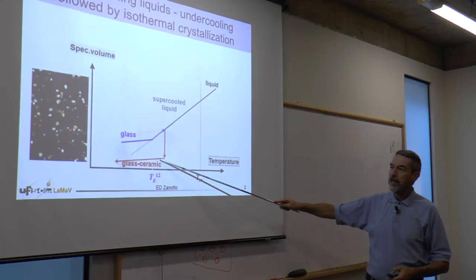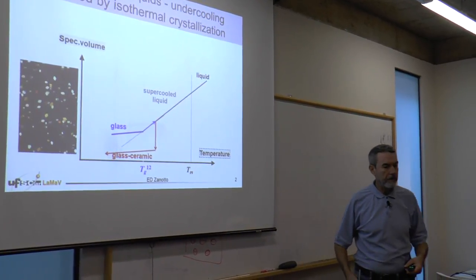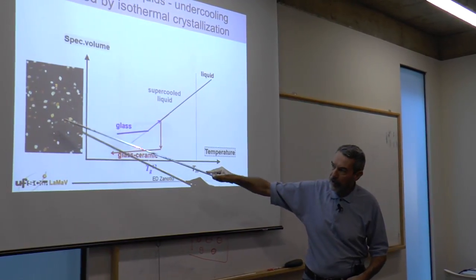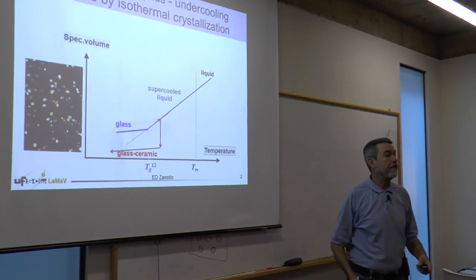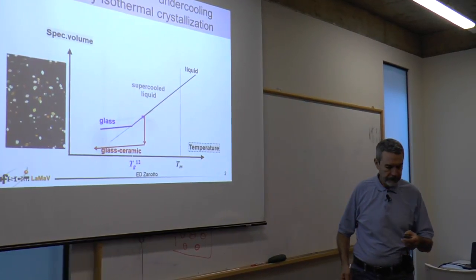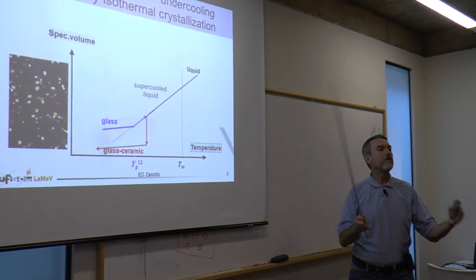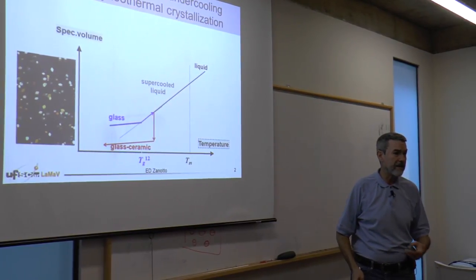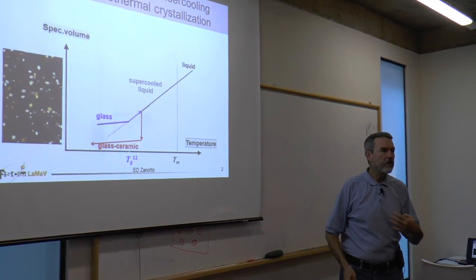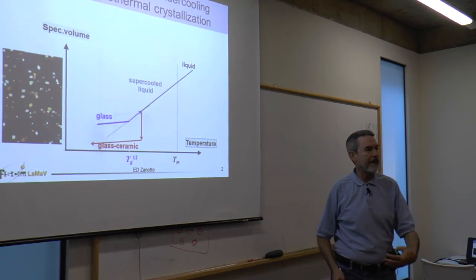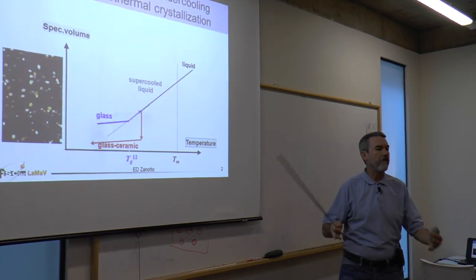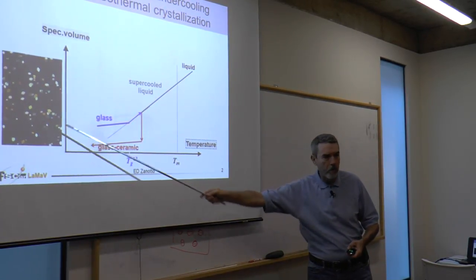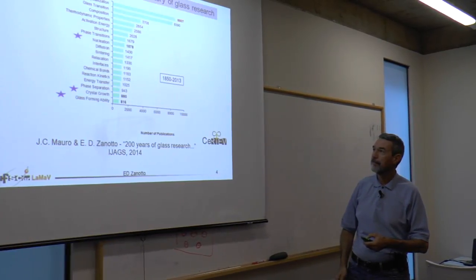In the end, if we produce controlled crystallization in the glass interior, then one can produce a glass ceramic. If crystallization is uncontrolled, if it happens from the surface, from impurity particles, from defects, in the end, we do not get a glass ceramic. We just get a devitrified product. Glass ceramics are produced via controlled crystallization of glasses.